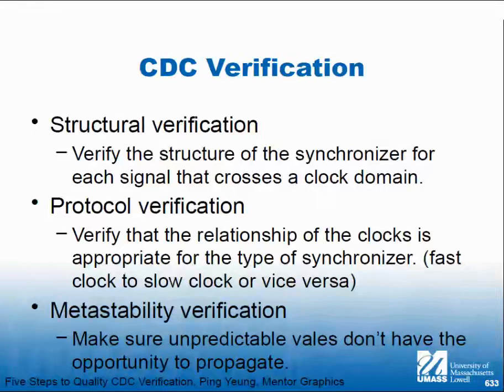So just as an example, FPGAs, it's not as bad as it used to be, but it used to be virtually impossible to send an FPGA to space because they're SRAM based, and SRAMs are particularly susceptible to alpha particles. The atmosphere filters out the alpha particles, but of course, when you're above the atmosphere, there's nothing to filter them out.